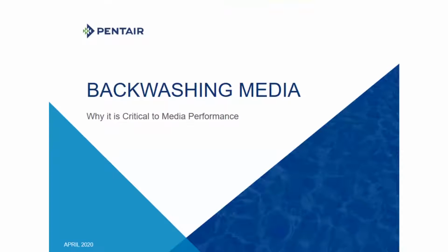So backwashing media, and why is it critical to media performance? It's a fundamental thing. Anytime we put anything in a tank and run water through it, that media in that tank is going to act as a filter, no matter the purpose of that media.